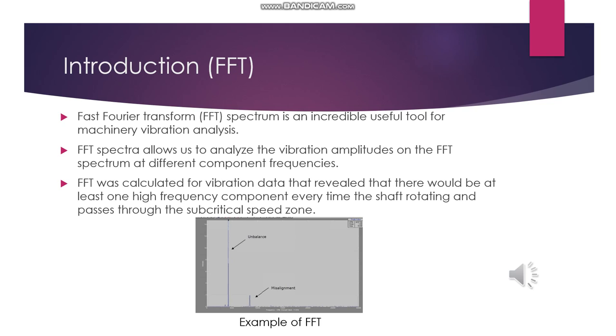Okay, for the next point, FFT spectra also allow us to analyze the vibration amplitudes on the FFT spectrum at different component frequencies. And for the last point, FFT was calculated for vibration data that revealed that there would be at least one high frequency component every time the shaft rotates and passes through the subcritical speed zone.